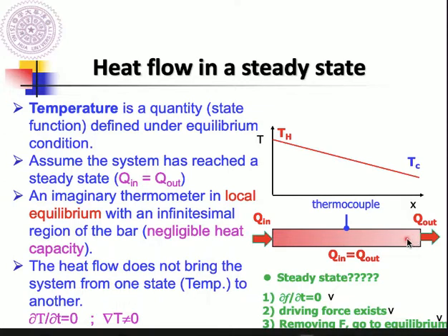So in reality, if you want to get this profile and observe the phenomenon of steady state, you need to use a tiny probe for this thermocouple and avoid heat loss through the thermocouple. Otherwise, the results you measure will be a bit different from these results.